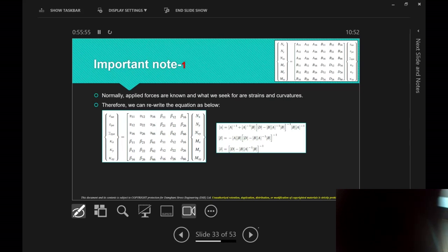Above, we just correlated forces with respect to the strains using the ABD matrix. You could also say, you know what, I want to associate strains with forces. Essentially, taking the strain to one side, you invert that ABD matrix, and it will give you alpha, beta, and all of that basically. And if you want to know what alpha, beta, delta are, it's all given to you. You can use Excel to find them. So we can do it in terms of force or in terms of strain. It's up to you, depending on the problem.